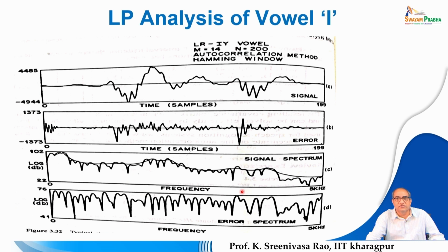And here I just introduced a new term, LP residual, linear prediction residual. It is nothing but the error signal that is generated in the process of linear prediction analysis, right. In the linear prediction analysis, the input is a speech signal, and for this speech signal, while trying to minimize the error, we compute the set of coefficients, and then whatever minimum error is observed for the given set of coefficients is known as the error signal. This is also known as excitation, and also as the linear prediction residual. So, all the terms mean the same.